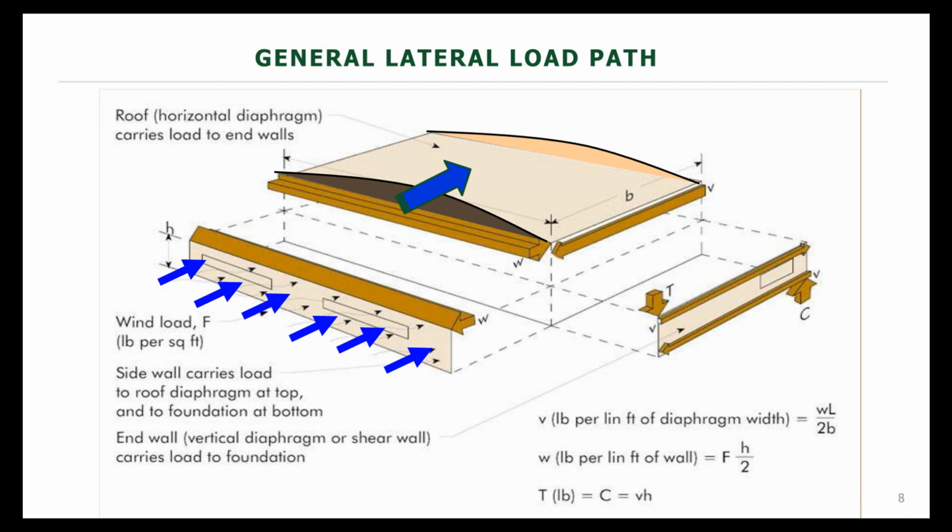You may sometimes hear them referred to as vertical diaphragms. I'm not a huge fan of that term, but it's certainly not an incorrect statement to refer to a shear wall as a vertical diaphragm. And indeed, when you start looking at the designs of shear walls and diaphragms, they do have many similarities. So it's not necessarily that much more difficult to design one compared to the other.